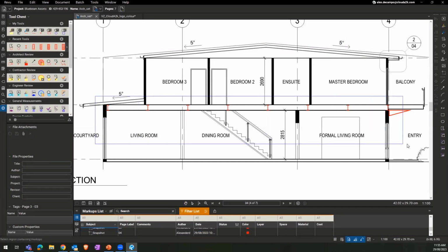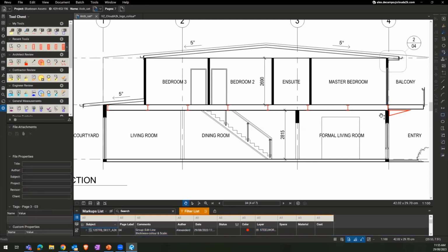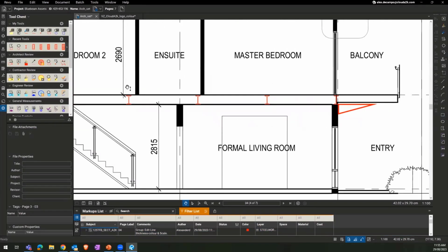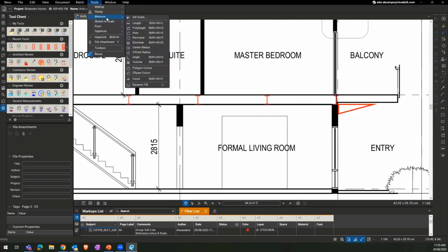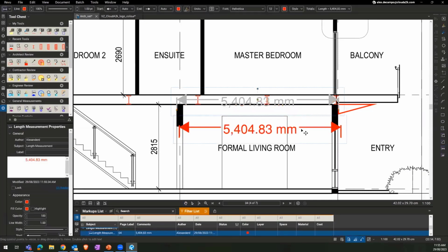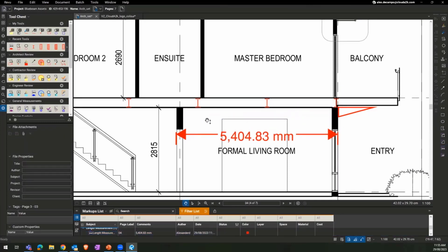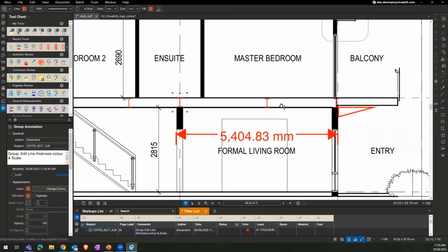So in between each one, the thing you could do is take a dimension. Between these two areas, I'll drop one in and measure the length from the outside of that wall to the outside of this one. Once I know this distance, I know that I'm at 600 centers. Then place the first one here, and the last one. And if you know how many beams, it'll do it for us.